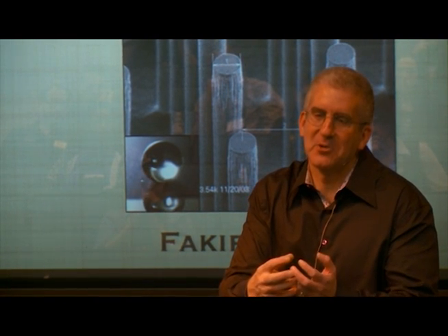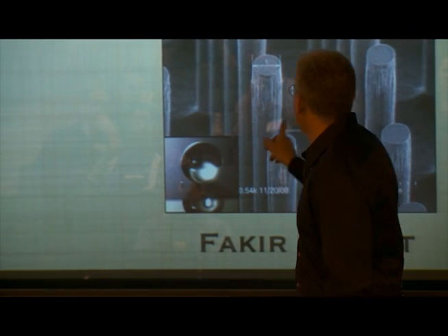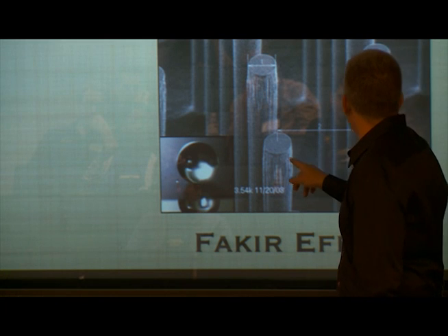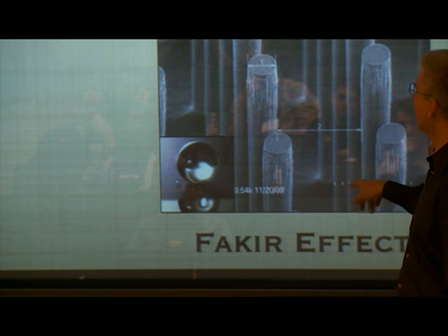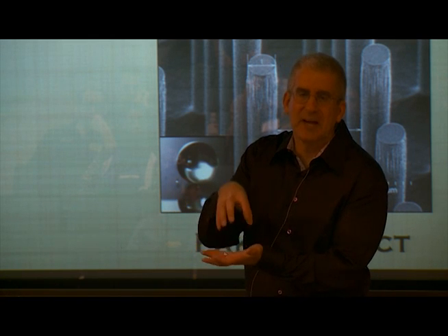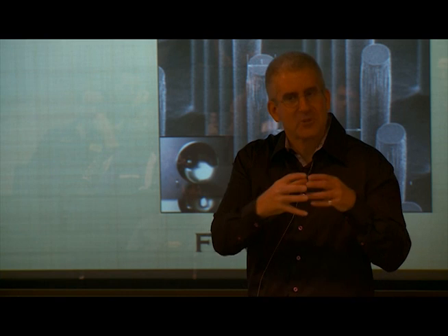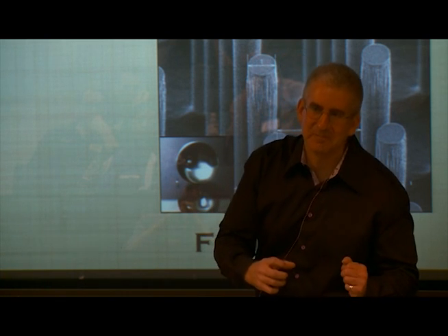So again, it becomes energetically favorable. Here's a picture of the fluid drop sitting on this manufactured surface. By the way, this is 100 microns here between the pillars. So you can think about this. If you try and push this fluid drop down, it has to wet a whole bunch of surface area there. That's energetically unfavorable. So it sits on top like the Indian mystic.